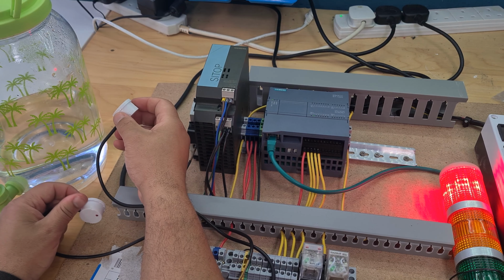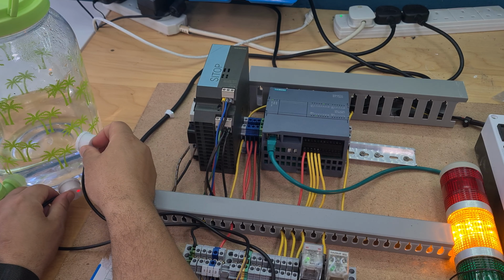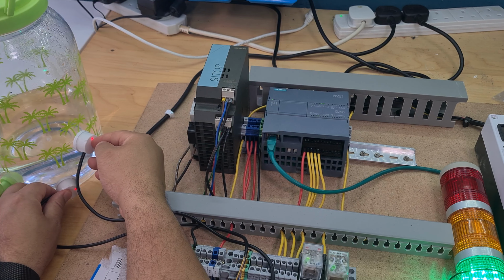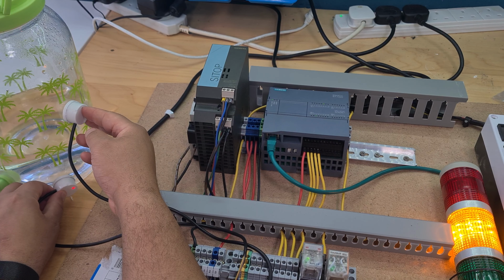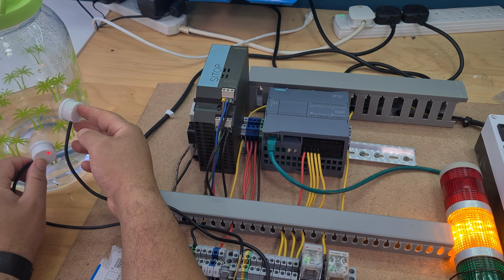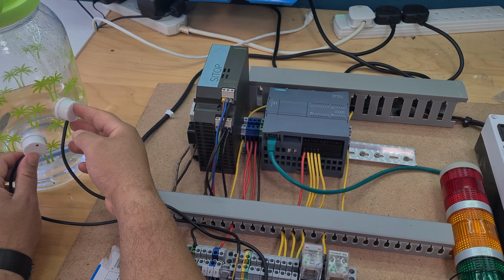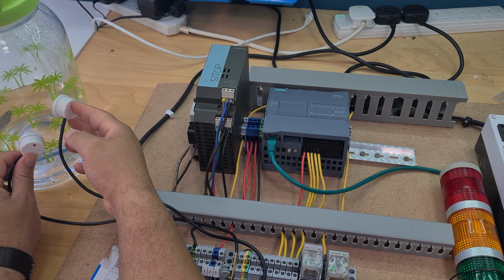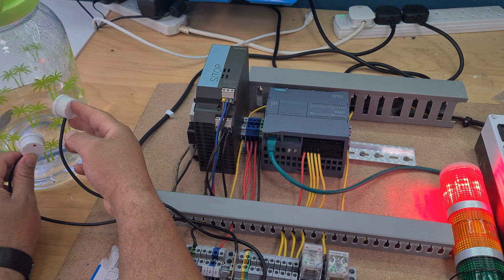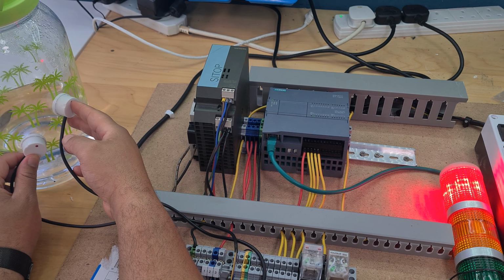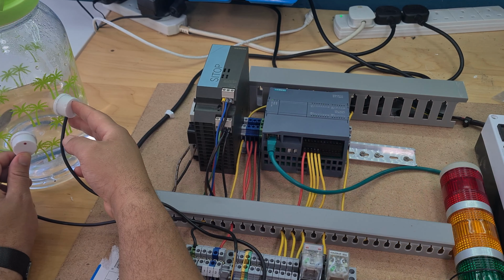So if I have my low level switch and then my high level switch, I'm green. Then it's going to say, okay, I've lost my high level, and if I now lose my low level within 10 seconds, I will trigger a fast fall alarm. It tells me that you've just lost all your tank fluid in a quick time, like a burst pipe, and you've just lost all your oil. That's a big problem, so maybe you want to send an alarm out to everybody.